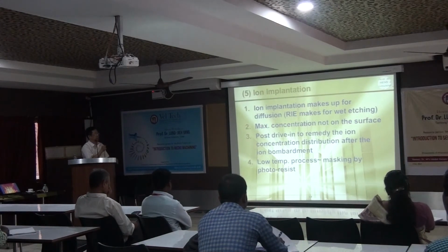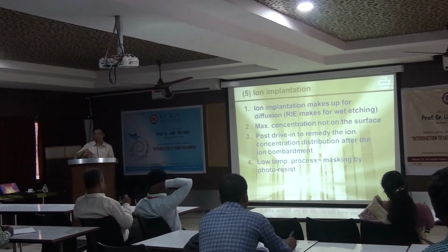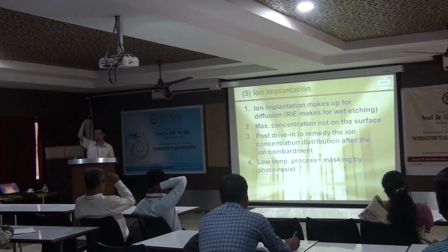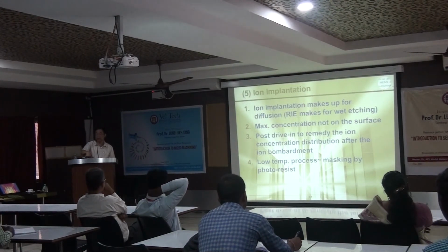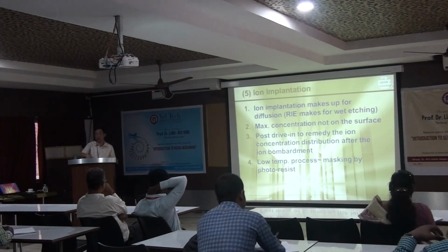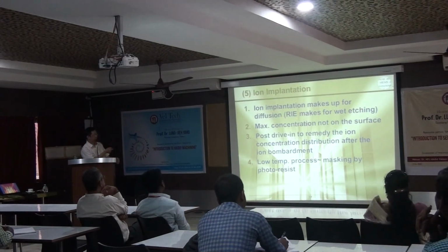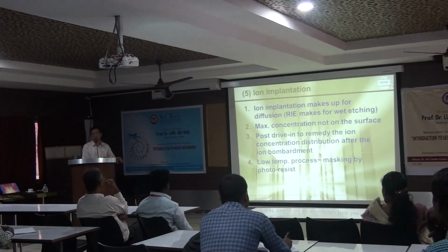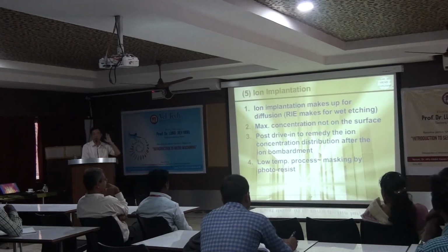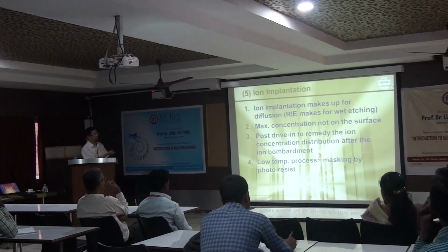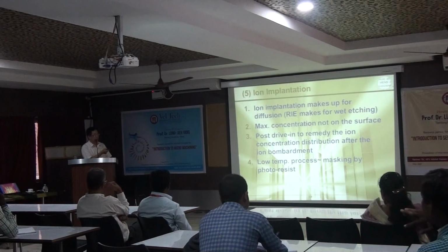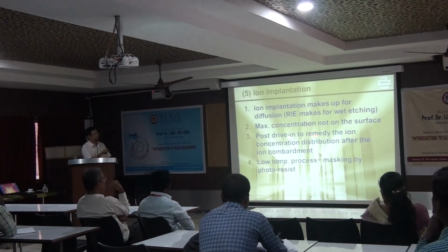So we call it ion implant. So the maximum concentration will not be on the surface, but underground, under the surface. Because when you touch the surface, it can penetrate, finally stuck. So the maximum dopant area is underneath the surface. So we don't use the pre-deposition. We use ion implant to do the doping directly. But you need a little bit of drive-in. Drive-in doesn't need to be done for a long time. We use the post drive-in to try to remedy the